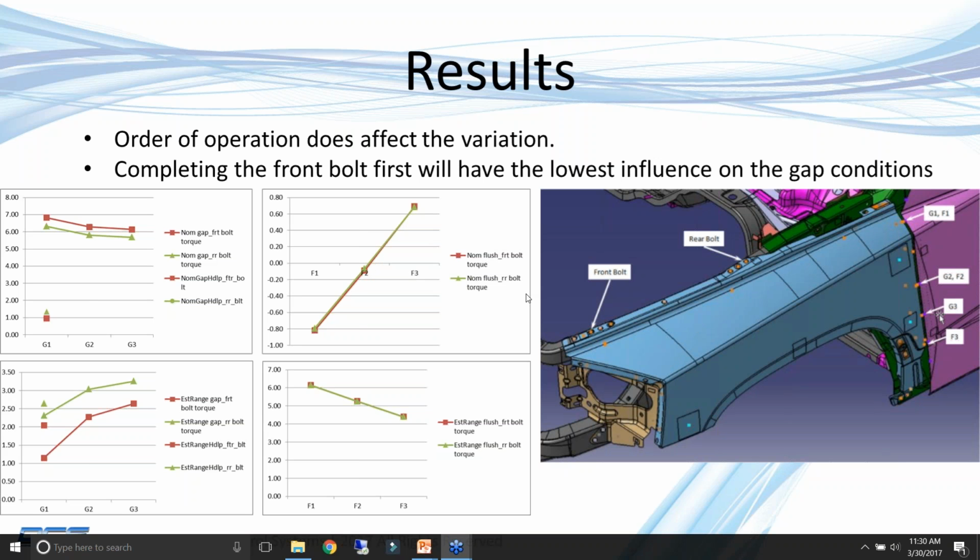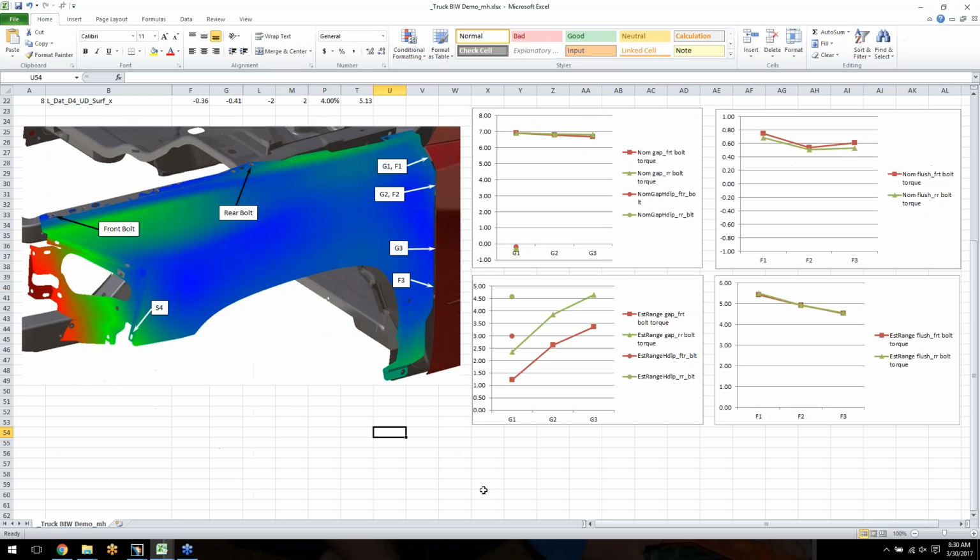Okay. There we are. I'm going to start again with the Excel sheet because it's easier to talk on it. A fender assembly: the fender outer, there's a bracket here and the reinforcement behind this area. They come as a compliant assembly, so I assembled them on a fixture on the side and then brought them to the body. The body I treat as rigid.